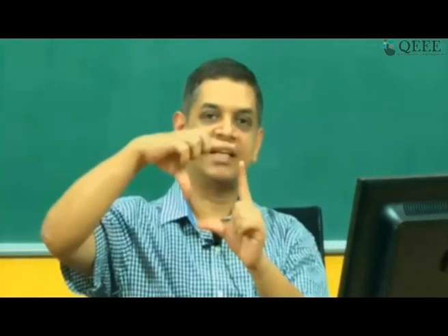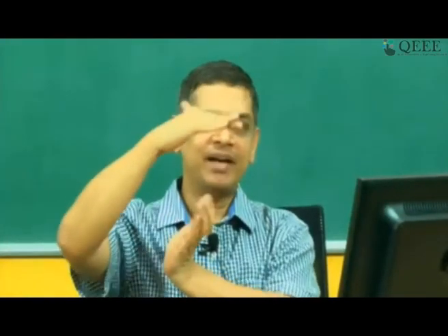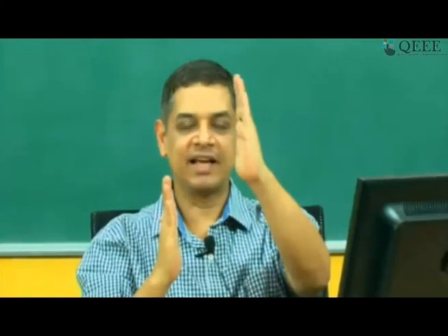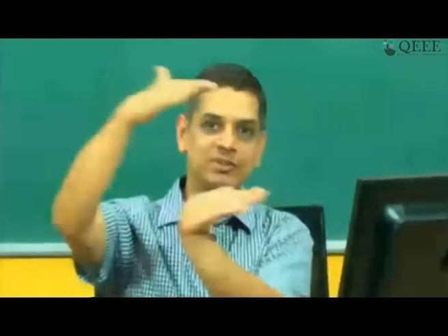Complementary shear, as I said: if you apply shear in one direction, like vertical shear, then there has to be a complementary shear, because this is giving a clockwise rotation in one direction. So there has to be a complementary shear which will give rotation in the other direction. And the actual path is basically the path in which the load deformation curve goes. Maybe you are clubbing that question with something else.